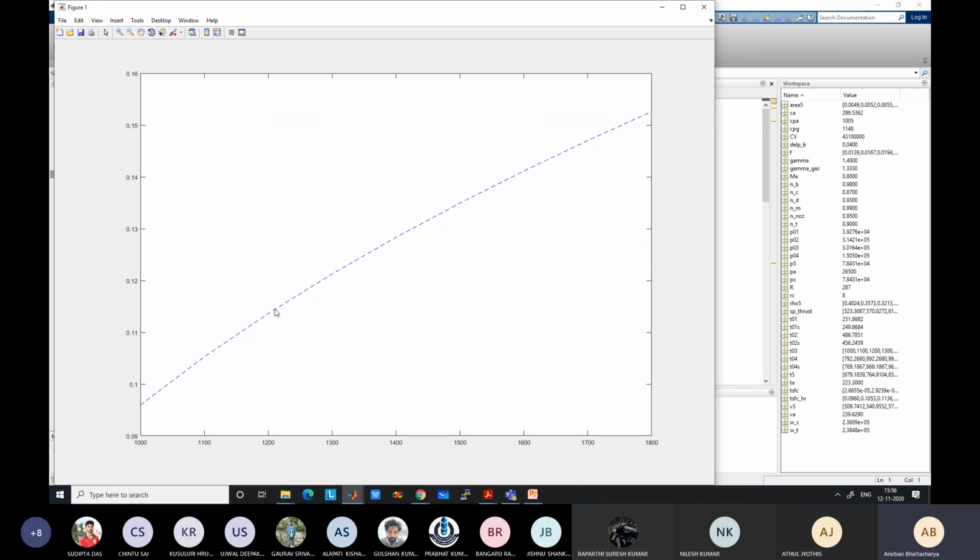And you can see that it is just a linear type of plot, where the fuel consumption keeps on increasing with increasing turbine inlet temperature. Okay, specific fuel consumption, not the fuel consumption, will obviously increase. There is no doubt about it, because if you keep on increasing turbine inlet temperature, your combustion process is much longer because we are keeping the compressor pressure ratio fixed.